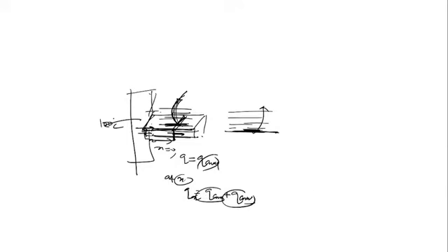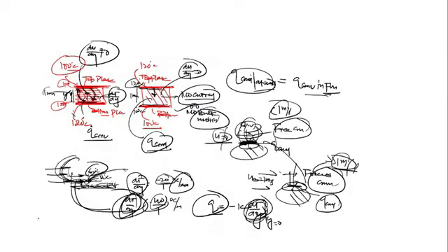Similarly, within the solid wall, is there heat transfer by convection? No, it's only conduction, because in solids convection is not possible. Convection is only in the fluid. And in order to carry out pure conduction in the fluid, you must restrict the bulk motion. And how can I restrict it? I had shown you through this example. Is conduction and convection somewhat clear now?